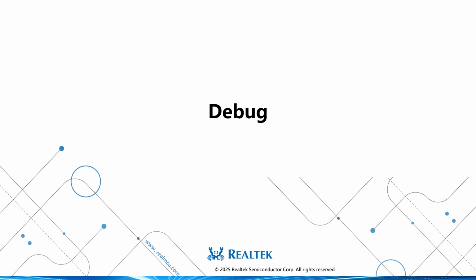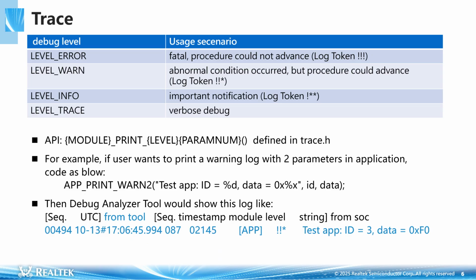Start by introducing the debugging-related content. Printing logs is the most common operation. Currently, the supported log method involves directly transmitting the address of the string and parameters for assembly on the tool side. This approach saves MCU time and allows for the output of logs with higher bandwidth.